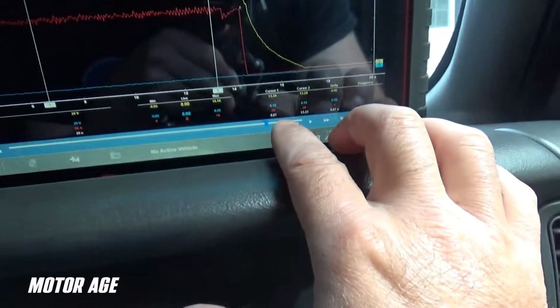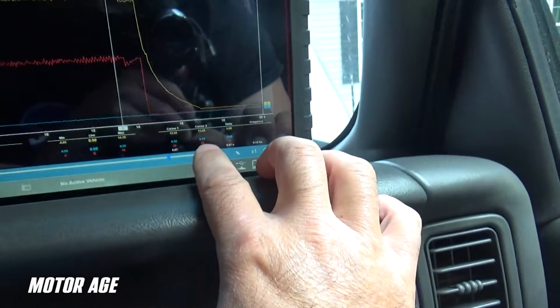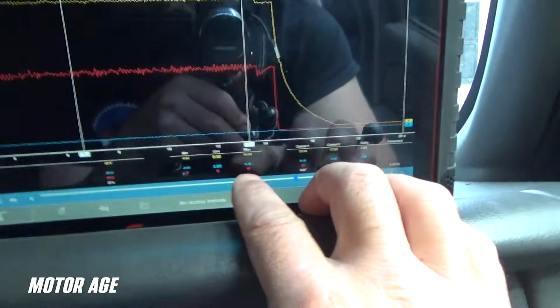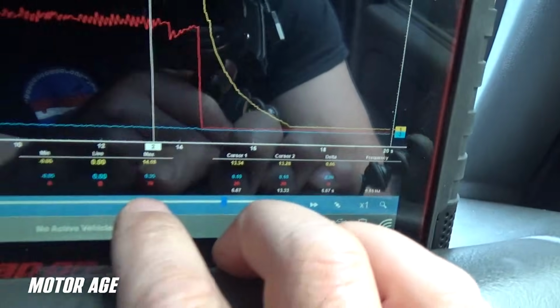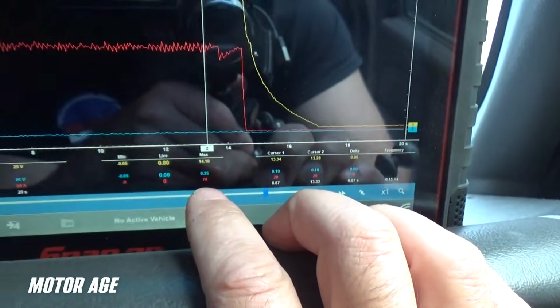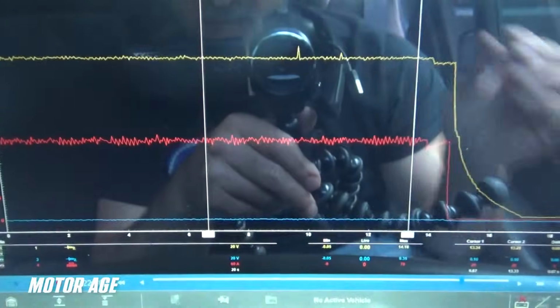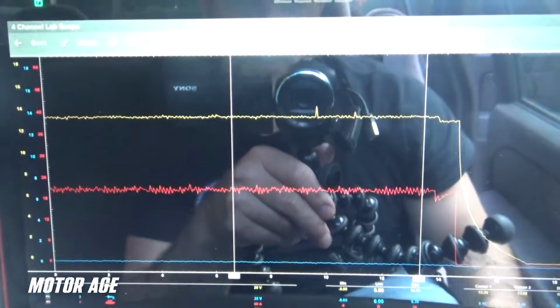And both are indicating, as they should, the same 20 amps. However, it also shows a maximum inrush current of 70 amps. So let's keep that in mind as we pursue this, especially when we put the new components in. We'll see the difference.